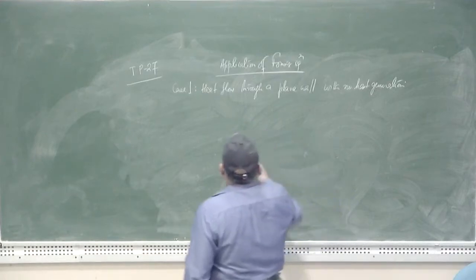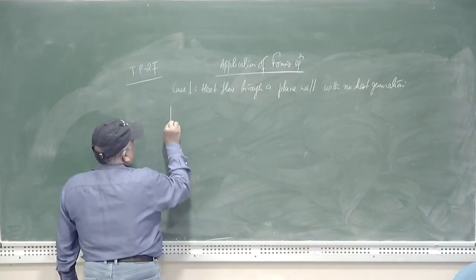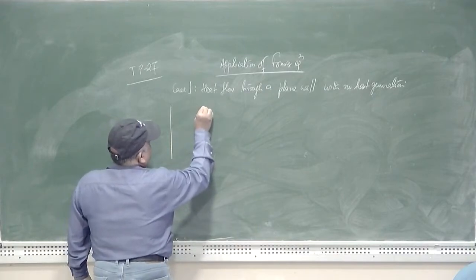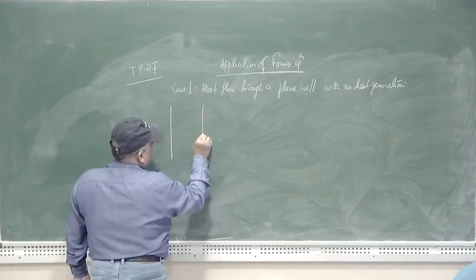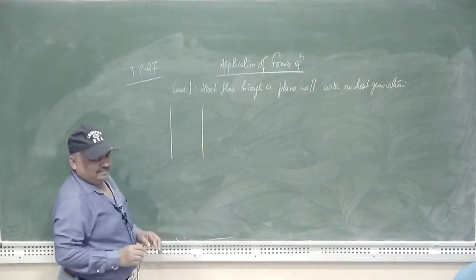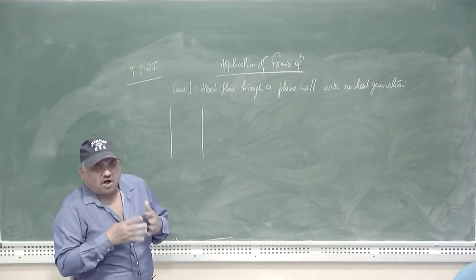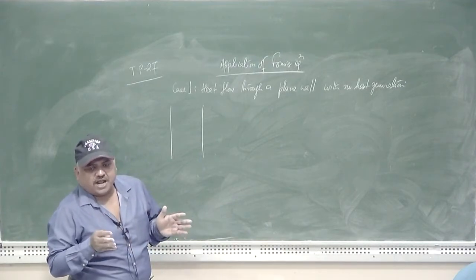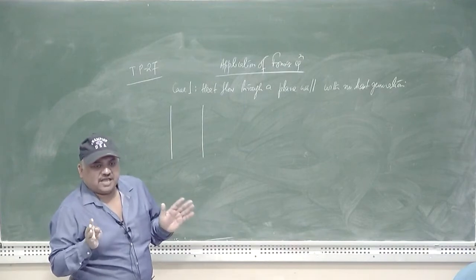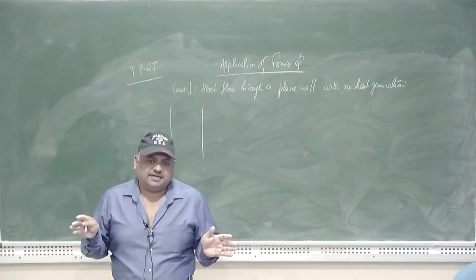So let us consider a plane wall. I am mentioning the plane wall because only the x direction is going to be considered here, by putting the assumption that the dimensions of the same plane wall along the y and z axis are such that the heat flow along those directions may be neglected.